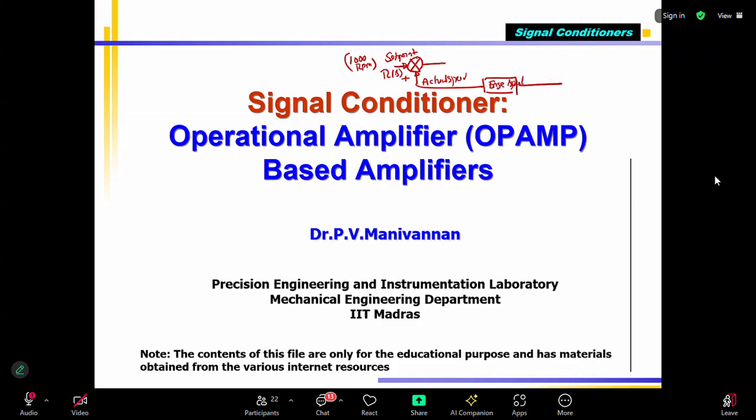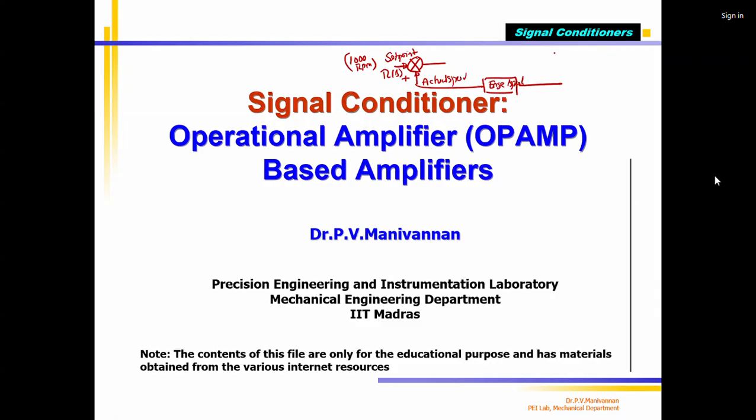Now this is my engine. Here I am controlling the injected fuel quantity. We know that if the fuel quantity is varied, torque increases, and automatically engine speed changes. The output is engine speed, omega S. This is my output. I am measuring it using a sensor, the engine speed sensor which measures omega of the engine.